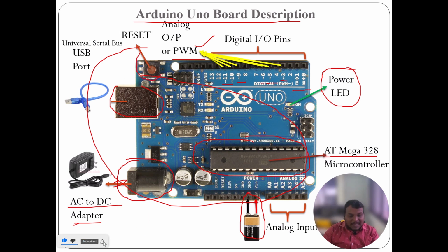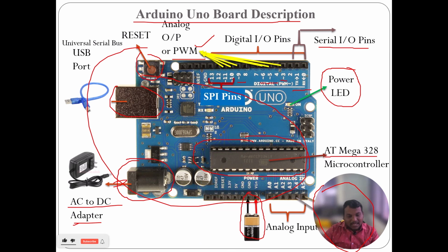This is the reset for the microcontroller. This is the serial input or output pins. This one is the I2C communication, SDA, SCL. And next, pins 13, 12, 10, 11 are the SPI pins. And this one is the ICSP header.